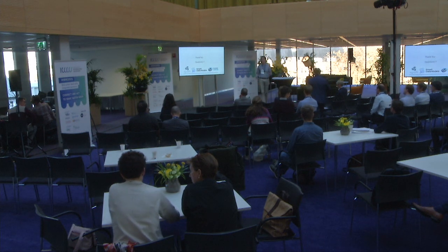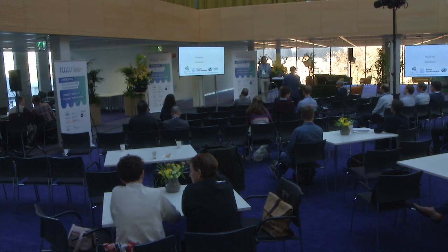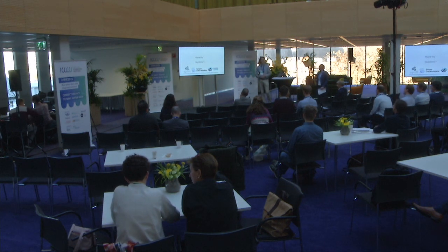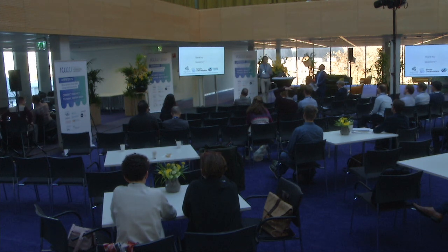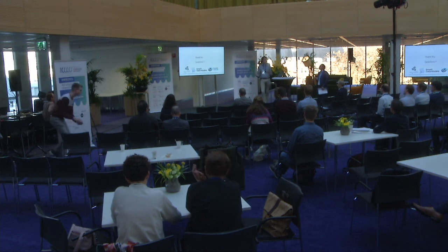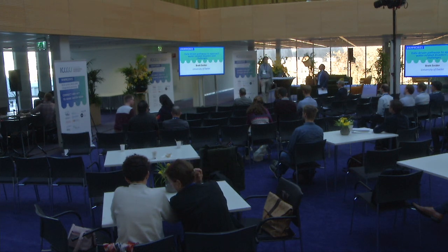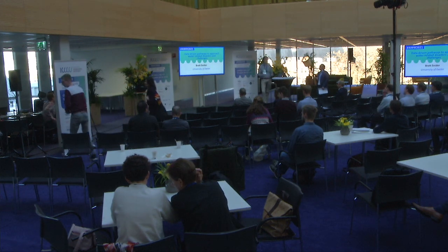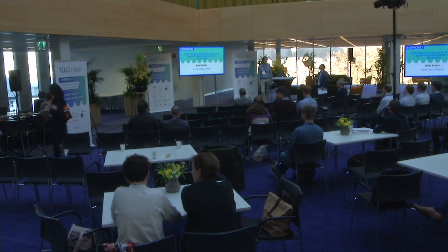Yeah, I think that there's two main parts to that. So there's the leak detection from the algorithmic standpoint. And so that would be the important part, is having the data and accurate data as well. Having more sensors in the network is always great, but the sensors cost money. But then from the pinpointing of the leak with the leak detection crews on the ground, there's a variety of techniques that they can do, through correlation methods, or moving temporary sensors, that can also improve the search area.